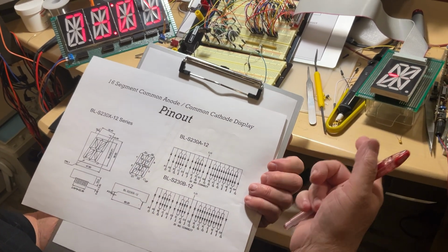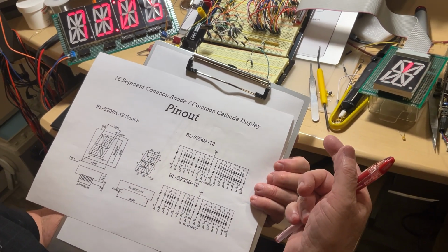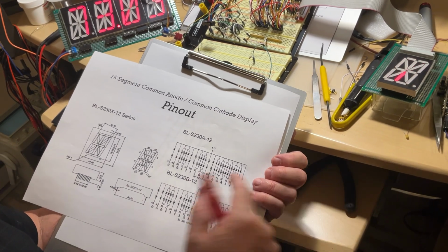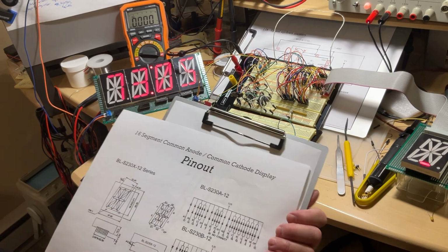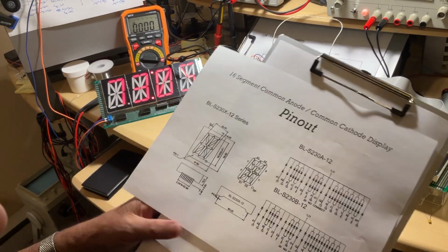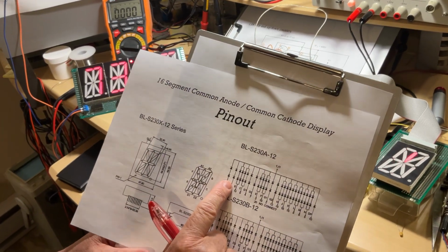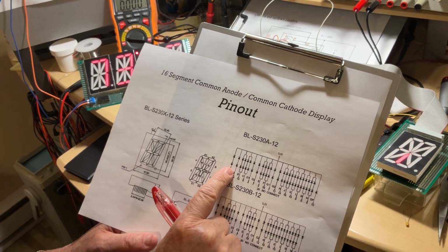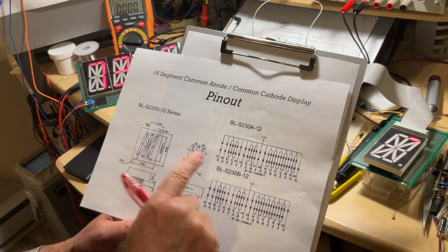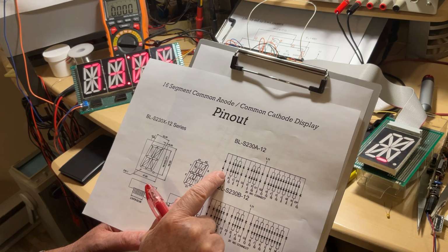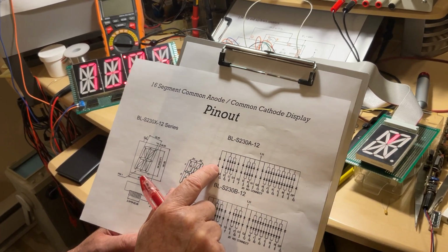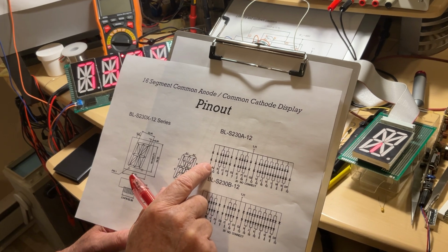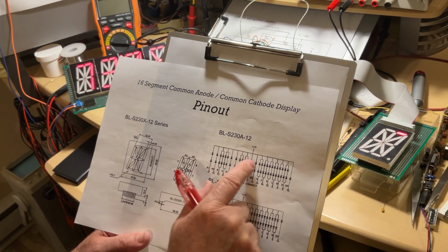Because if you try to measure them, you're going to find out with the multimeter that it's practically not possible to measure them, because the multimeter position for the diodes was made practically to measure rectifiers. For the LEDs we measured them some time ago, and when there are 2 of them in series and you want to measure, you're going to find out that the meter does not indicate anything.